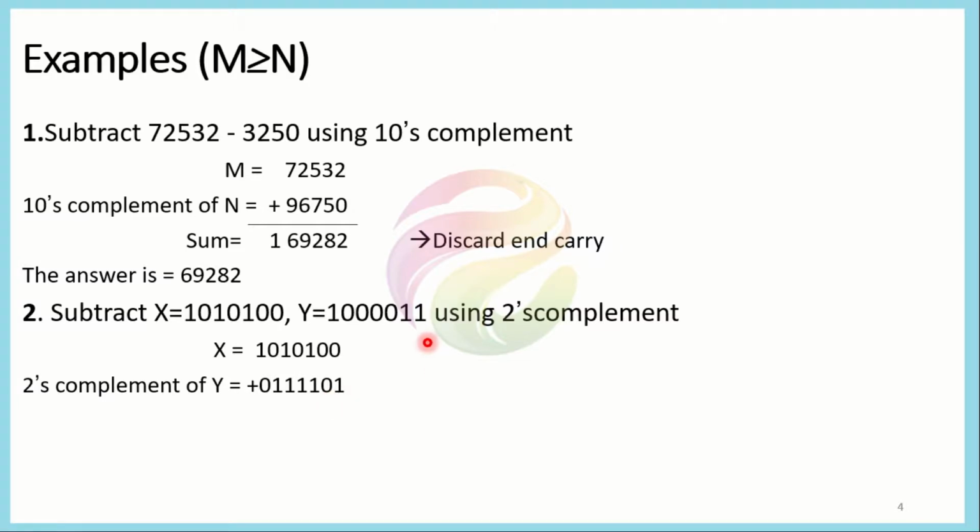If you remember, we keep all the least significant zeros as they are till we reach the first one, and we write that first one as the same. After that we just interchange all the bits, changing 1s to 0s and 0s to 1s. And now because we have taken the complement, we will just perform the addition, the standard process of column wise addition.